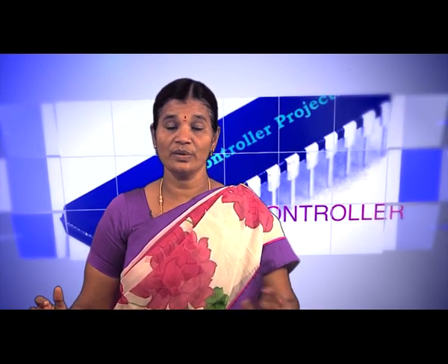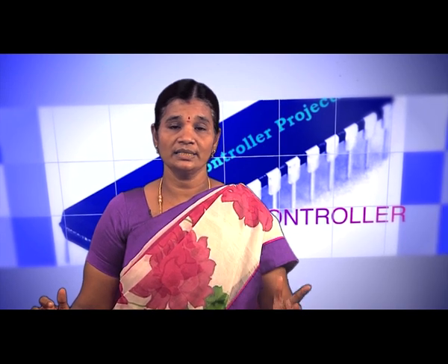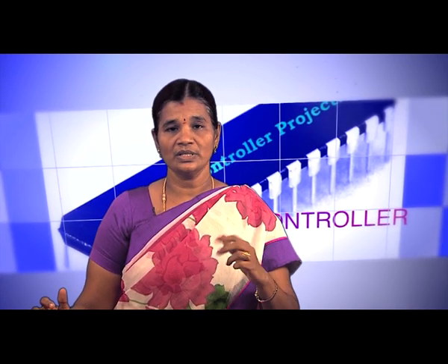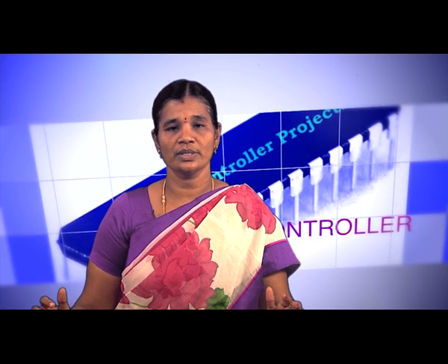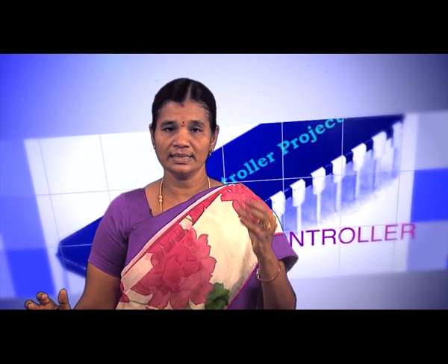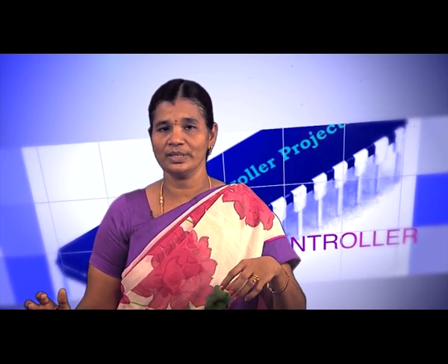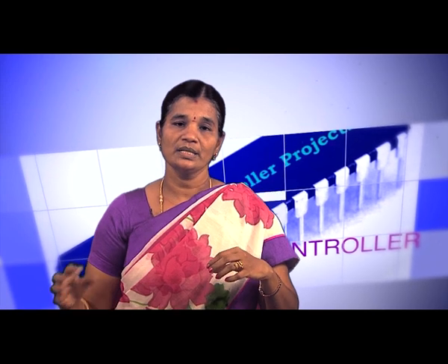In the branching instructions we have discussed conditional and unconditional. Unconditional means that without checking any flags, it immediately switches over to the specified location. During the switch over, the current content of the program counter is pushed onto the stack, and the new subprogram address is loaded into the program counter. The program counter then increments and executes the sequence of the program.